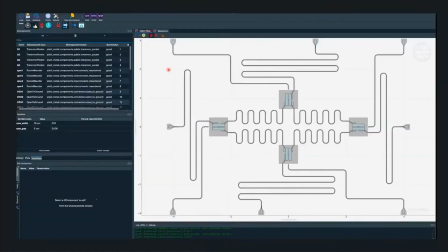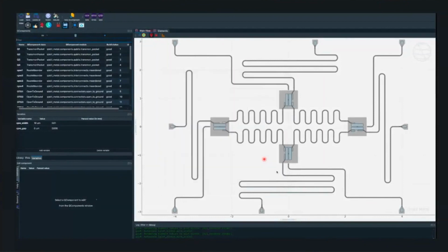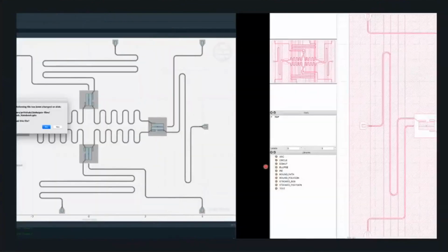So you click up here, the GDS renderer. The GDS renderer has a bunch of options as to what you want to export, what are the tolerances, do you want that, I guess we'll have to add, is it positive or negative mask, all these kinds of details. And so Priti and folks here have done some great work on creating this very nice renderer that just takes what you see in Metal and exports it into a GDS.